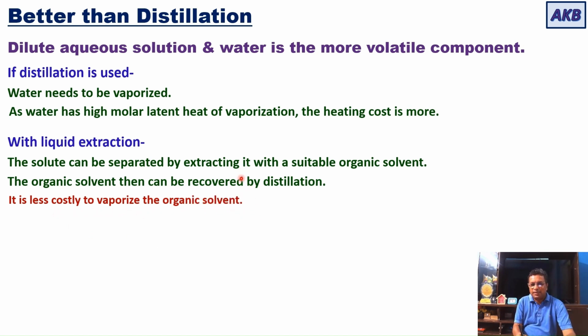So that's why this liquid extraction, you can say, is cheap as compared to distillation. Because in distillation you need to vaporize water. Water has high molar latent heat of vaporization, so heating cost is more. So if you use liquid extraction, and for that, if you use a suitable organic solvent, which you can easily recover by distillation, it would be less costly to vaporize the organic solvent. So in this case, liquid extraction is better than distillation.